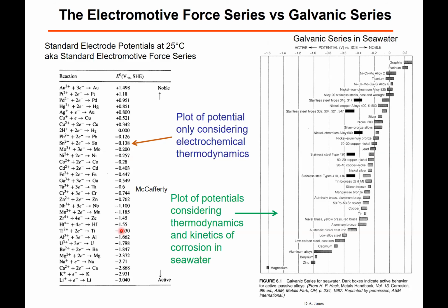So when you're doing corrosion rate studies, particularly in seawater, you really have to consult these data tables, or construct one for yourself in a standard way, to really understand if a material is going to be more or less active. Just referring to this table is not always indicative, and sometimes it can actually flip your conclusion. Would you be expected to know if nickel and titanium will always behave in this way?